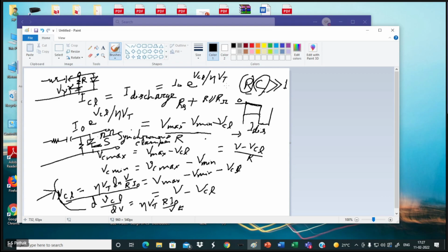And the second thing, if you are including the diode characteristic in your design, you should have one reference voltage V added here. So your fluctuation in the clamped voltage will be small and the level at which it is clamped will be large. I have now completed this module 2 and the tutorial that I wanted to talk about. Any question? I welcome.